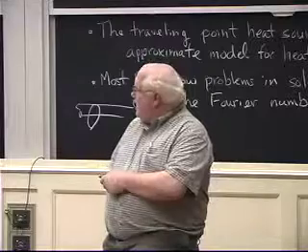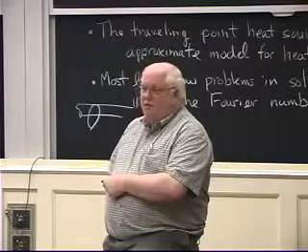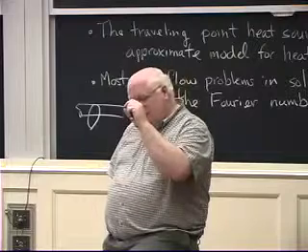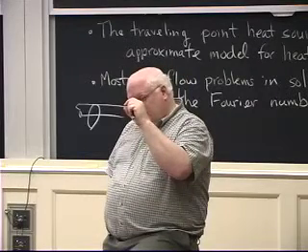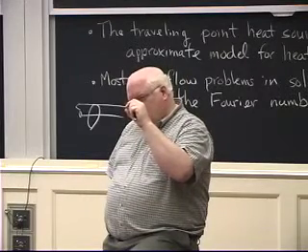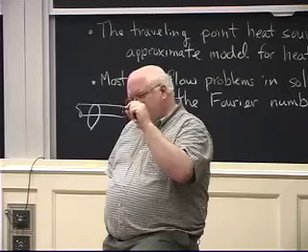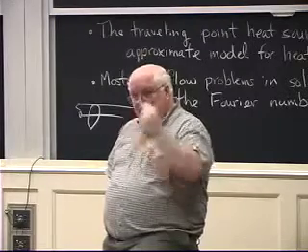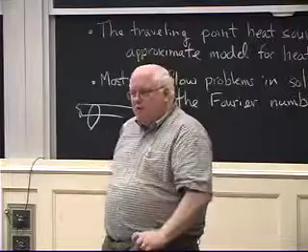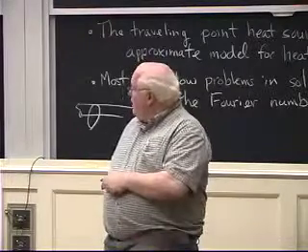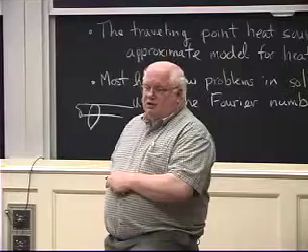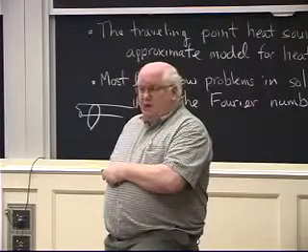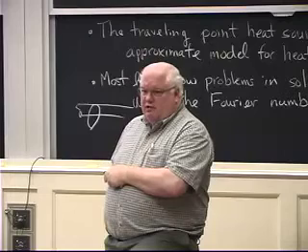So there is out-of-vacuum electron beam, but in general, if you want to make a high quality weld, that standoff distance, whether it's a 1/4 of an inch or 3/16 of an inch, is a huge difference in its penetrating capability, because the beam is diverging so rapidly in the full atmosphere. Lasers you can actually run in a vacuum and they run just fine, but it's the extra cost of the vacuum. Lasers run best in a gas of helium.